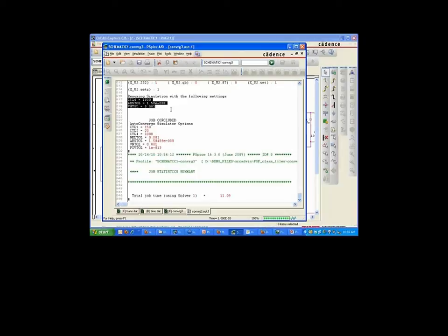You'll notice what it didn't do is just take everything you gave it for loose tolerance settings and use that. It really surgically pecked away at what you gave it and took what it needed but didn't take everything you gave it. That way your tolerance still stays as tight as it possibly can. While looser than what you wanted, it's still as tight as it possibly can be to get some results.